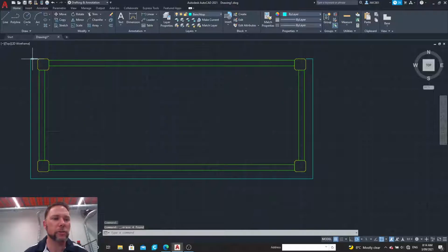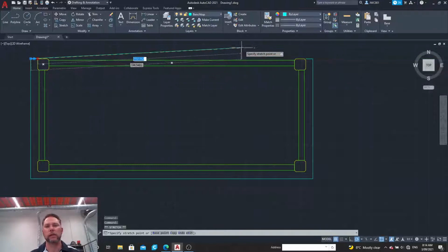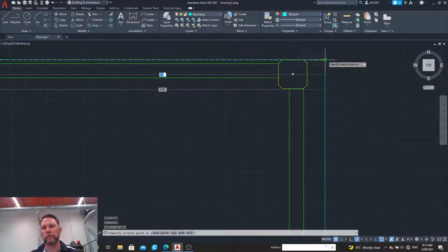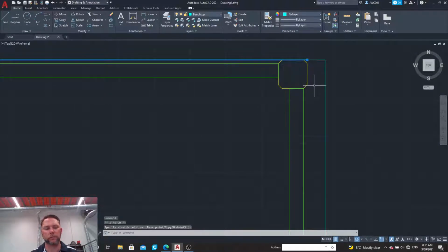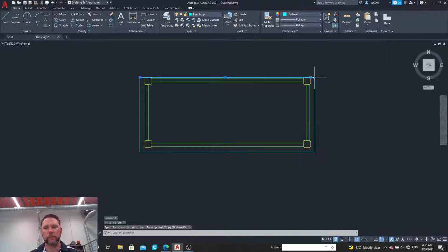Now I can join this up, select that, click on the ends, node point, and I'm just going to stretch it all the way till it joins with this one here. And then this also needs to be, I'll join these ones, modify, okay. So that is joined.